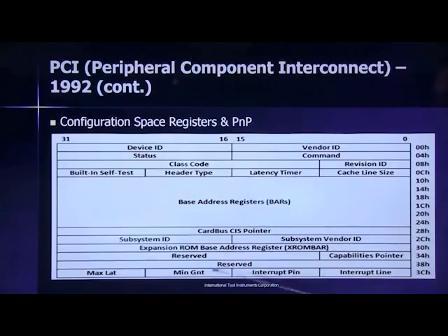The base address registers are used for letting the operating system know what memory and I/O ranges are needed by the card to do its work. So how this works is that the operating system reads the type and size required for each register bank. You might, for instance, have 4 kilobytes of I/O space, and another 8 kilobytes of memory mapped space that the card needs to do its work.